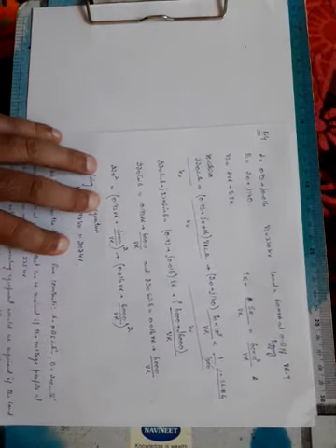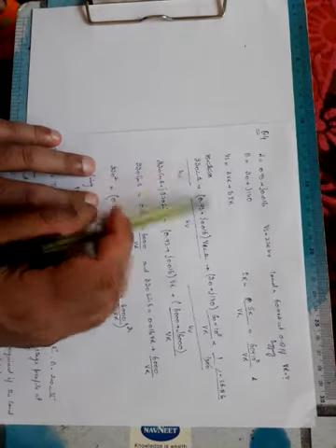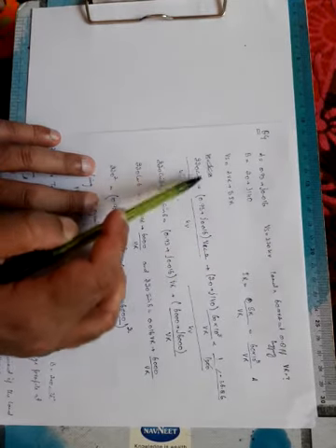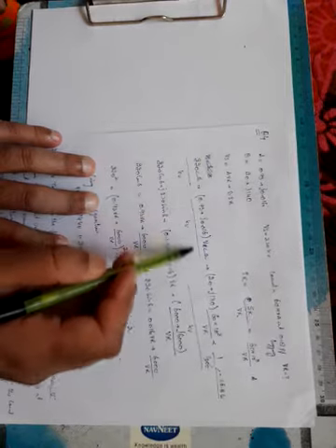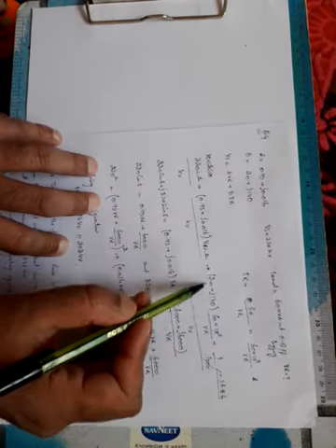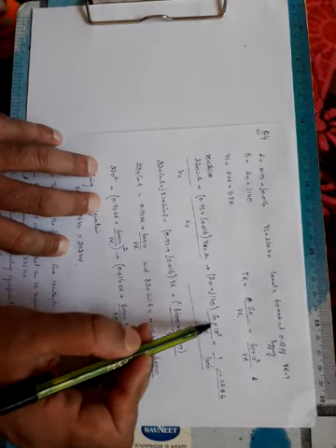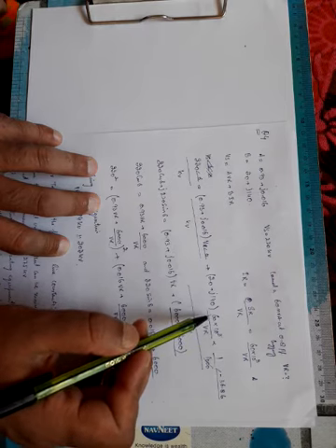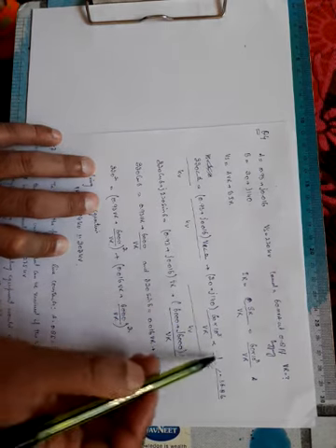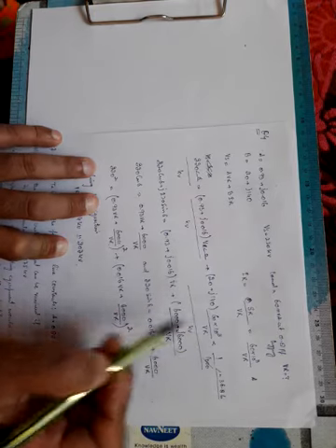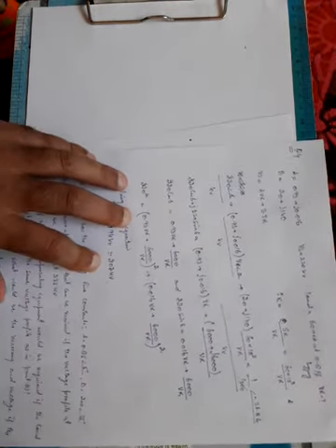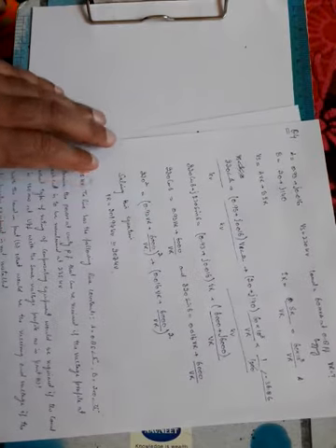Now you can see this 220 is actually in kV, that means this term is in kilovolt. Since this VR we are assuming to be in kilovolt, this term will also be in kilovolt. Now this is actually in ohms multiplied by current, so it will be in volts. To make it into kilovolt, we divide it by 1000, and it comes out in kilovolt. That 1000 and this 1000 will cancel out now. So, on proceeding, you will see that